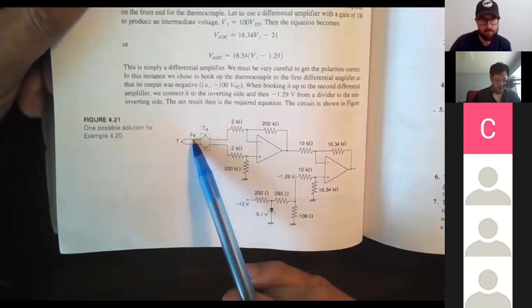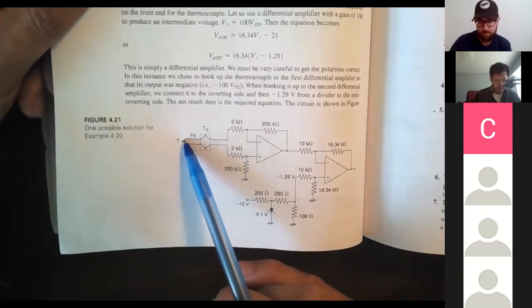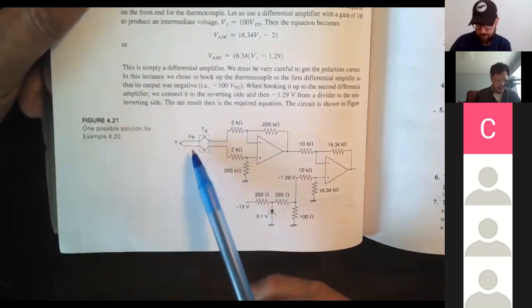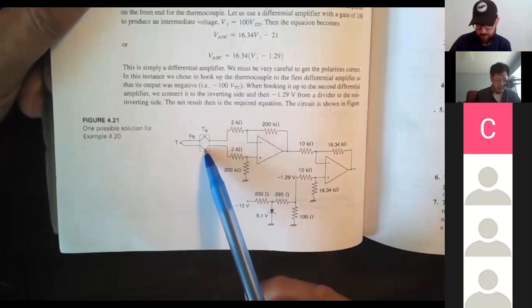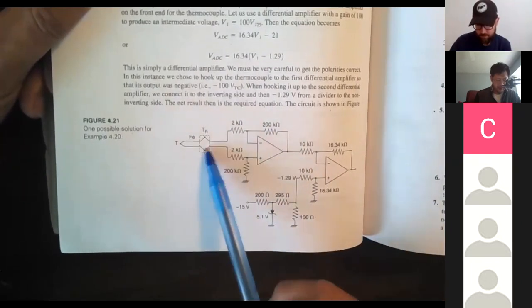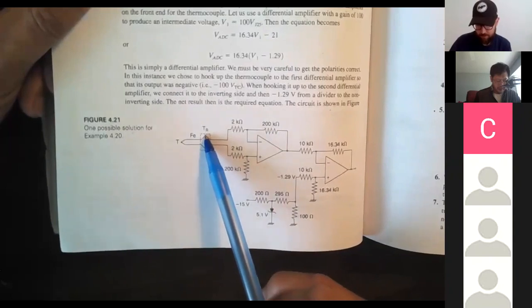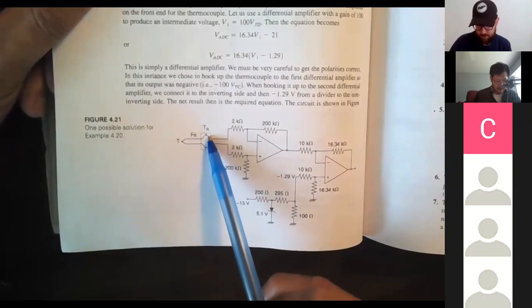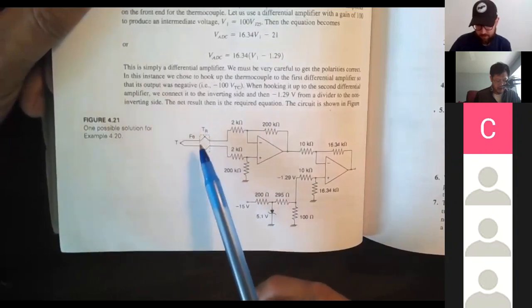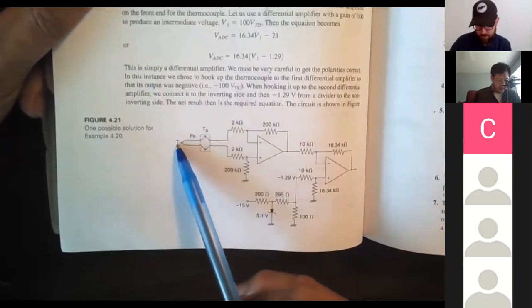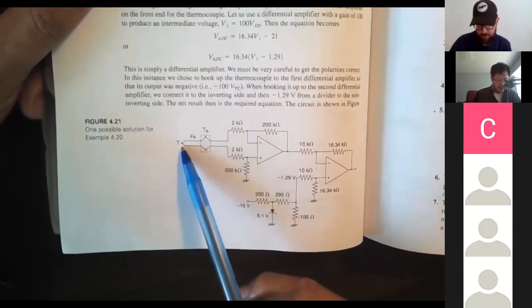So this is a type J, for example. One wire is iron, one wire is constantan. And then you make the connection right here to copper wires, and then you don't worry about the copper all the way through. So that junction is the second junction. You want to keep that second junction connecting point in air conditioning in the room. All right, that's the sensor.